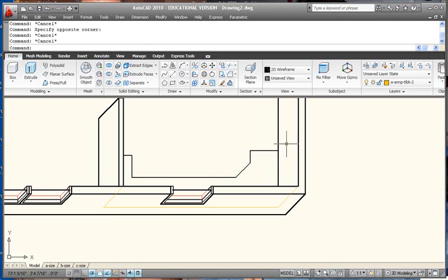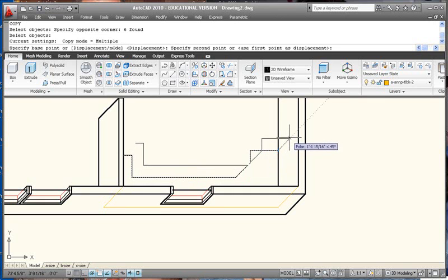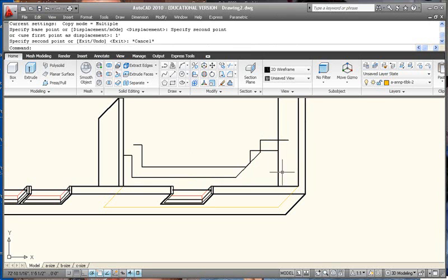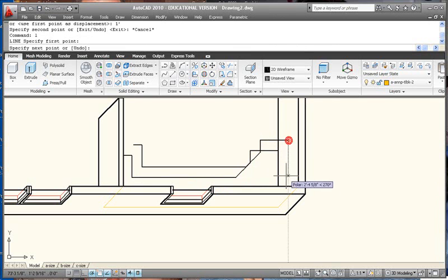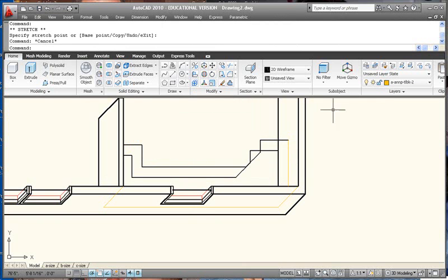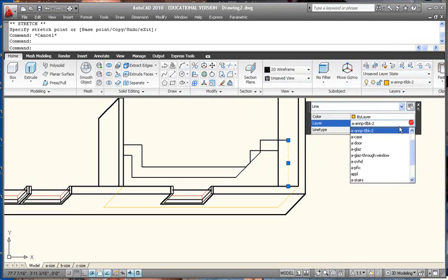Now what I want to do is draw the height of them, so we're going to end up generating up here a second edge to the cabinets. So I'm just going to copy the same lines that I have before and click on the corner of the line and add the same 45-degree angle we've been using so far, put in a distance of 1 foot. So now this edge here is representing the top edge of the cabinet, so I need to add another line there, and I need to add a line here. So this line here should be the same as the others that I've got going. So this should be on the case layer.